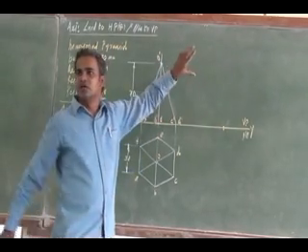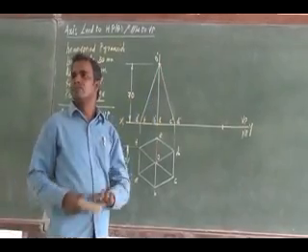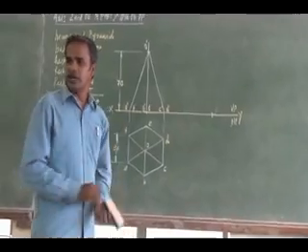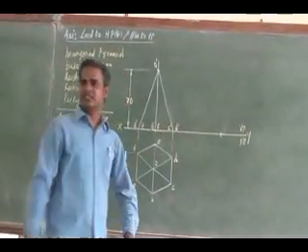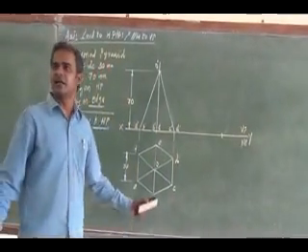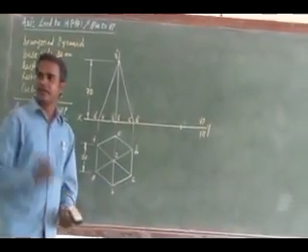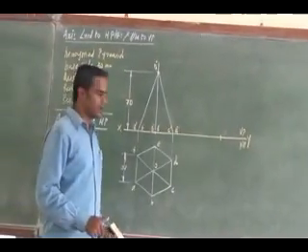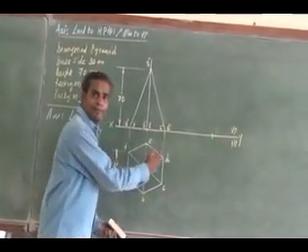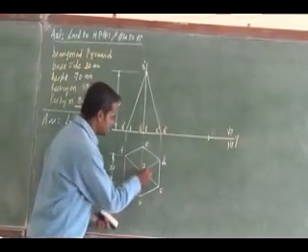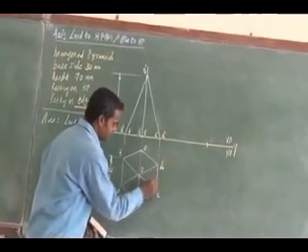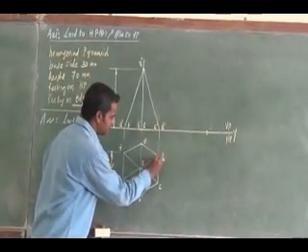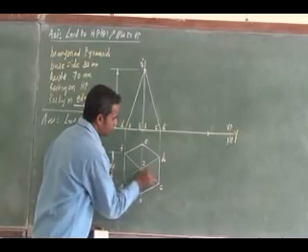Now, in the second step, I have to redraw this front view. So, what is the condition given? You see here, it is resting with the edge. Which is the resting base edge here? CD, right? Along that resting base edge there is a triangular slant face, CDO. In the top view, this is the triangular slant face I am talking about.